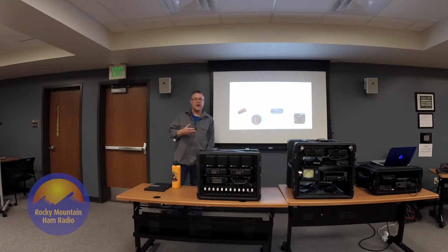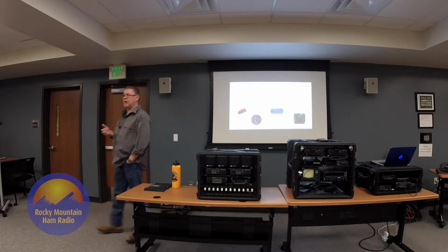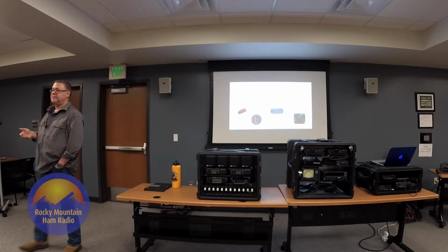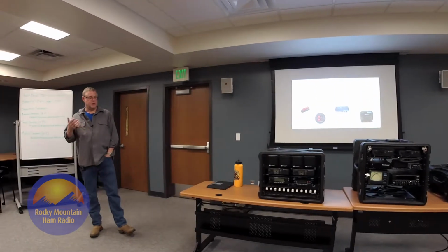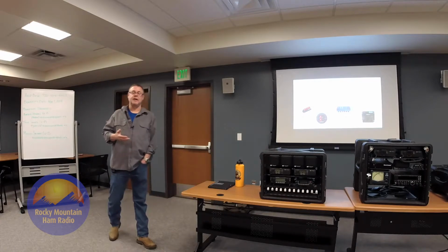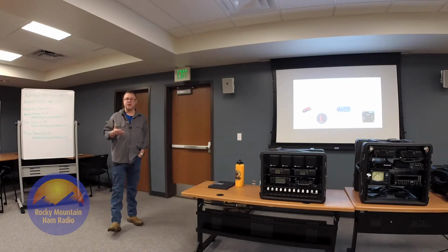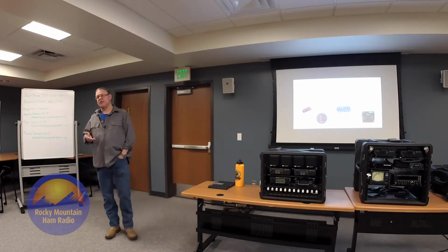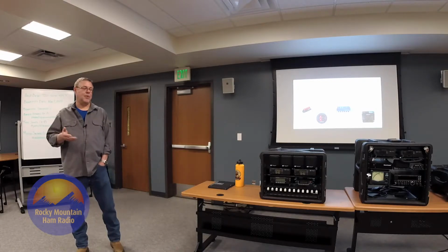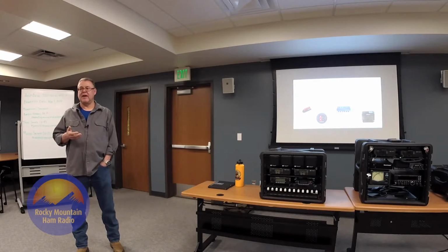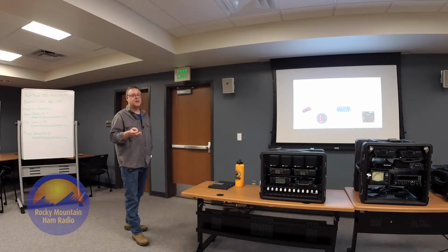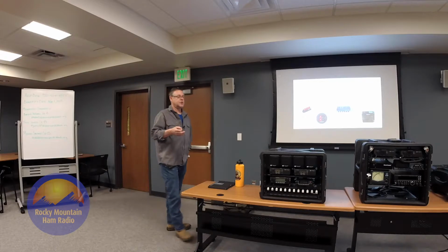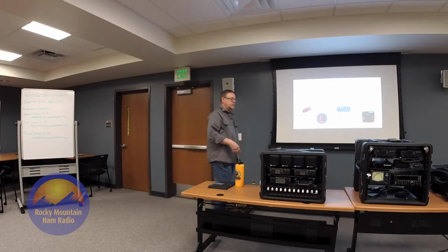But the other thing is isolation. They create power isolation between your batteries and your power mains or your power supply. Yes, you can hook up your battery in parallel with your power supply and let it run. It's not good engineering practice. You can do it, it will work. However, you're better off having some isolation of some sort. Whether you build it yourself with some diodes and rectifiers, or whether you buy one of these, or you use some other method,